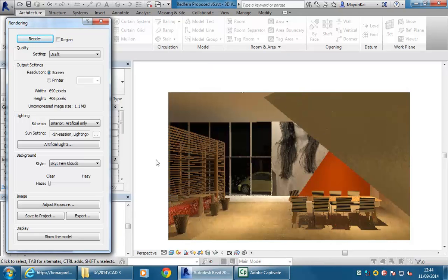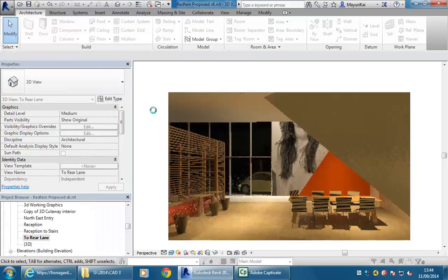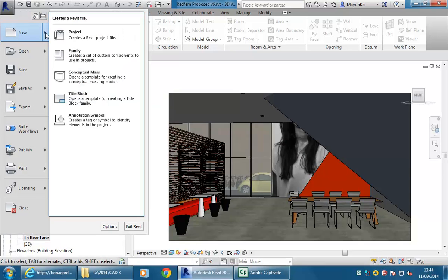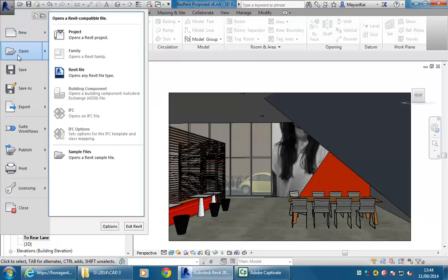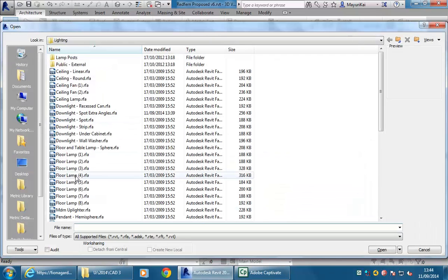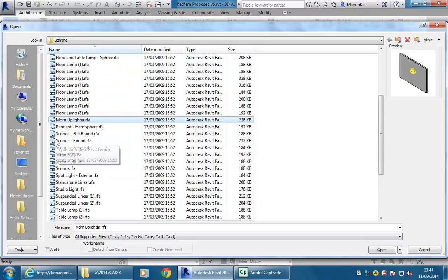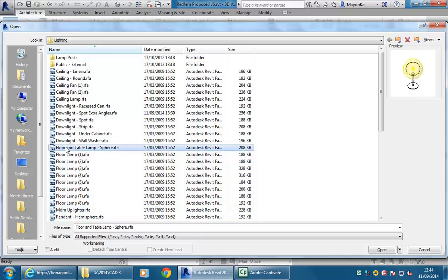And so then to just show you some other kinds of lights, if I go now, I'm going to make a new light family. You've got some pretty good options for the sort of light I'm going to show you in the library. Things like the linear lights, which let you move lights up and down without being hosted, and all those other nice things.